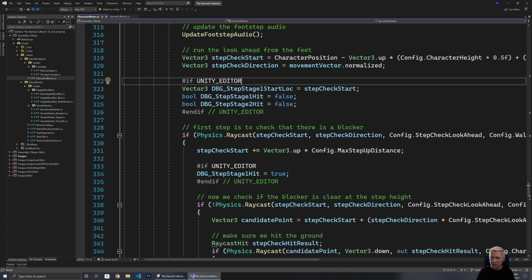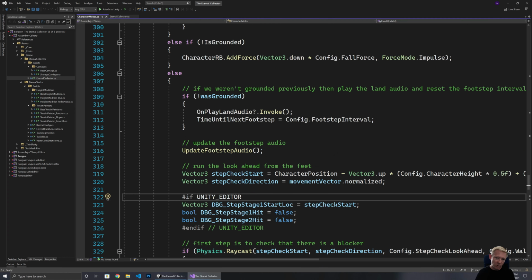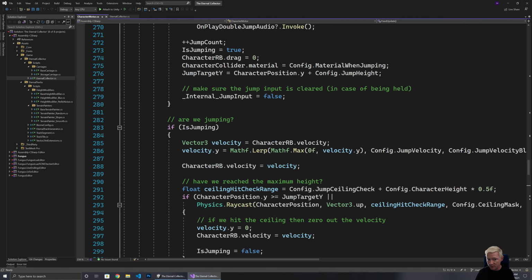And on a non-moving environment, that was fine. But in a moving environment, that position can actually be different to the rigid body position. Because when you access rigid body position, it goes through the physics system. So it's getting and setting data as it currently stands in the physics system. Whereas using transform position is not. And that was what was happening. There was stuff that was out of sync.